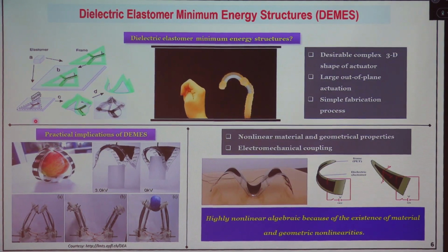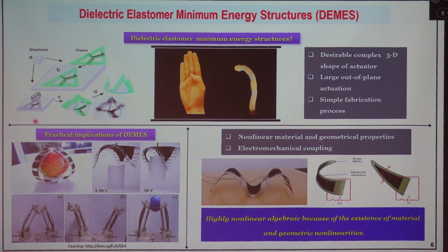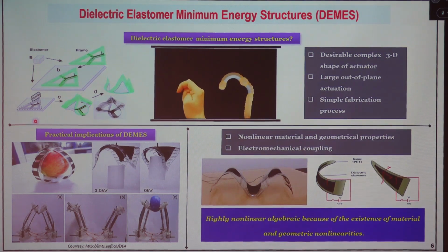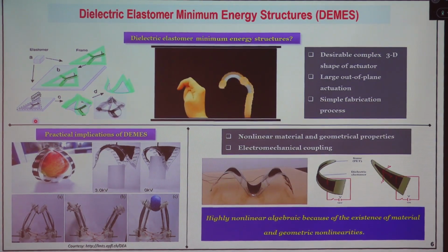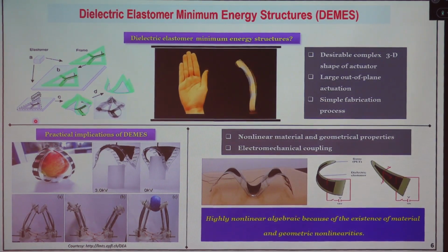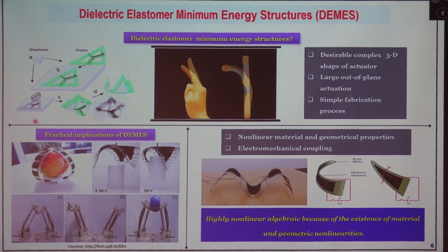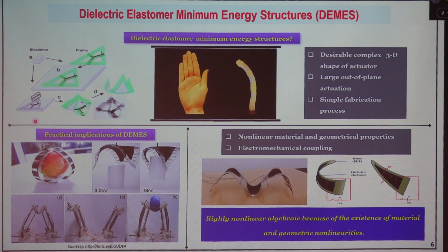The concept we are utilizing is that because of the pre-stretching of the membrane, elastic energy will be developed. Initially there is a membrane, and you provide equibiaxial, uniaxial, whatever stretching you are providing. Definitely some elastic energy will be developed in the membrane; stresses will be developed. Now you are using that elastic energy, which you have bound by a mechanical constraint.